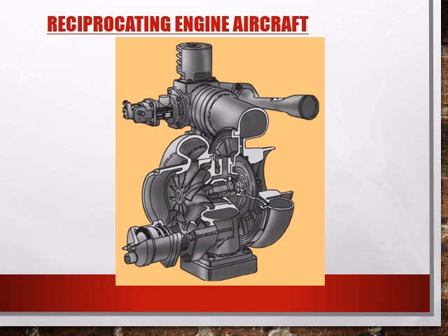There are three typical sources of air used to pressurize reciprocating aircraft: supercharger, turbocharger, and engine-driven compressor. Superchargers and turbochargers are installed on reciprocating engines to permit better performance at high altitude by increasing the quantity and pressure of the air in the induction system. Some of the air produced by each of these can be routed into the cabin to pressurize it.